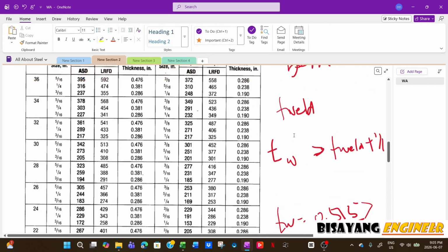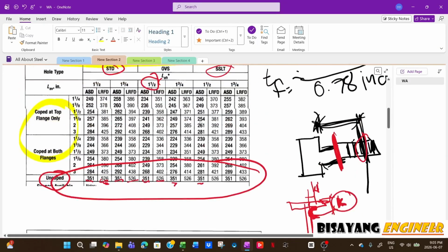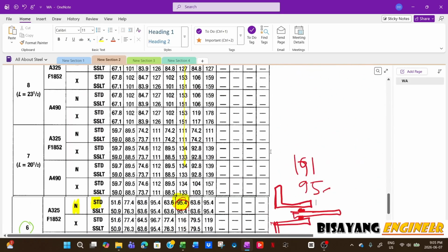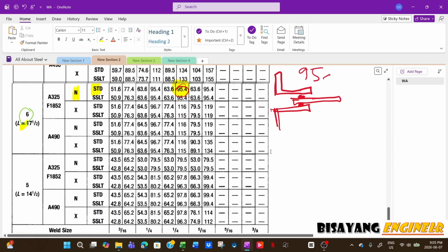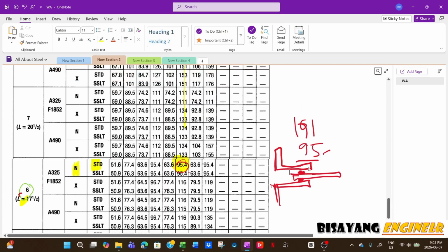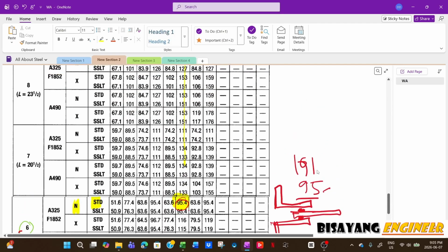So I won't be comfortable having a capacity the same as the demand. You have to have some kind of extra allowance. So if it was me, the capacity for 6 bolts is only 95, I will increase the number of bolts. So you need 20. Now, for some reason, if this is 7 bolts, which requires a 20 and a half length of plate, and then